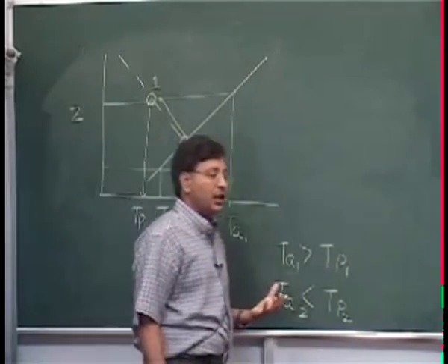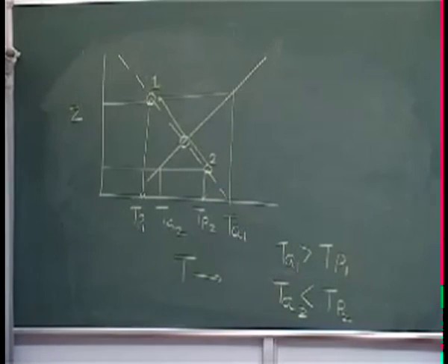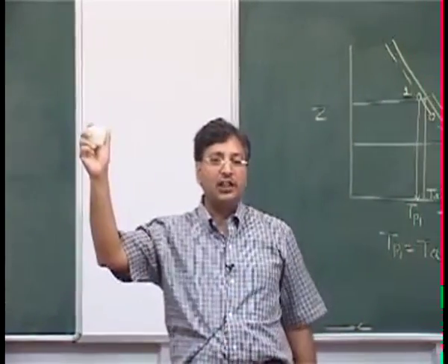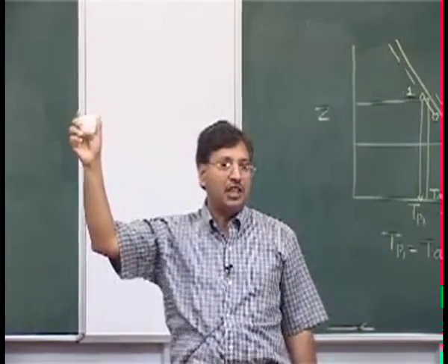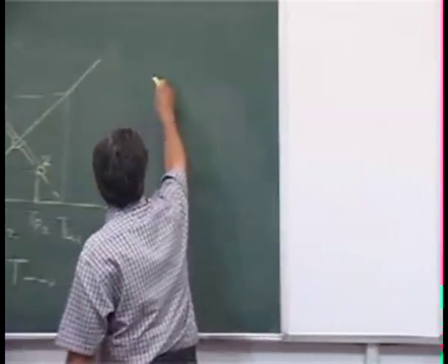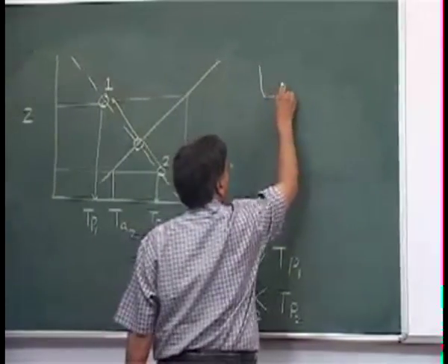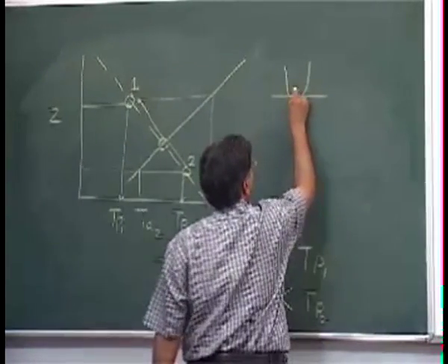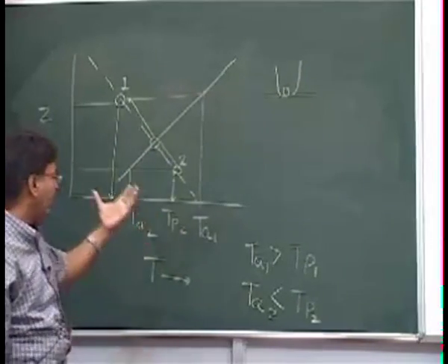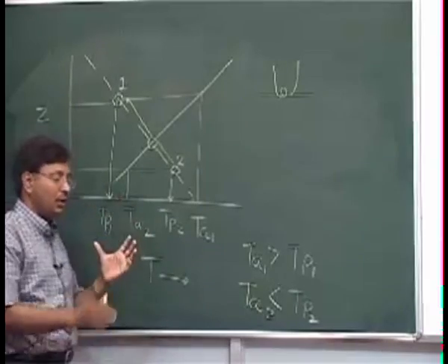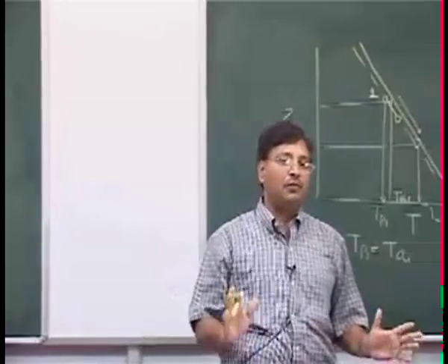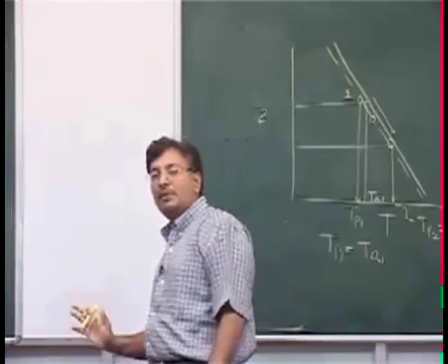Under these situations, it is something like this: you have a bowl. In the bowl you put some ball kind of thing, shake this one, and this is not coming out. It just stays wherever it is. For demonstration purposes or for writing this, I can make a ball like this. In the bowl I make a ball and then shake it. No matter how much energy I try to give this one, it is not moving. So things are stable. Pollutants don't travel, don't disperse vertically. They refuse. That situation is really very bad.